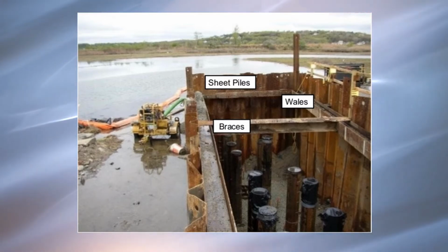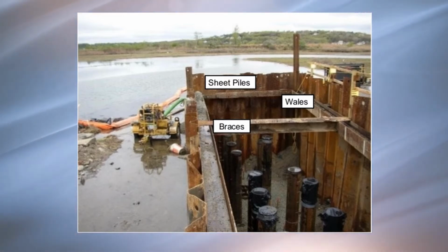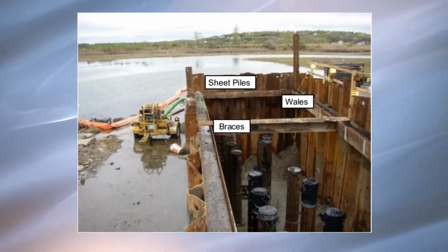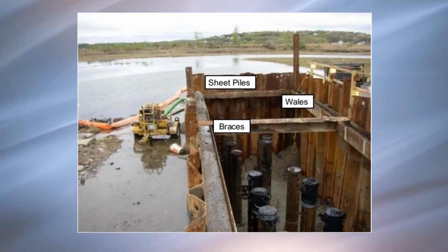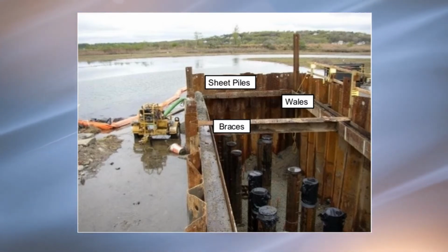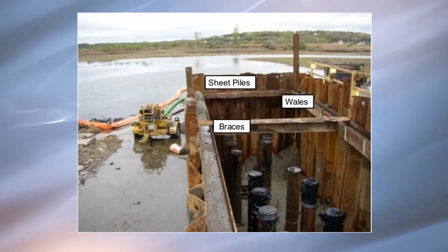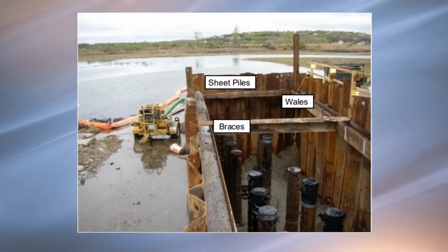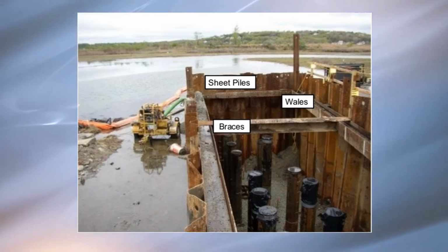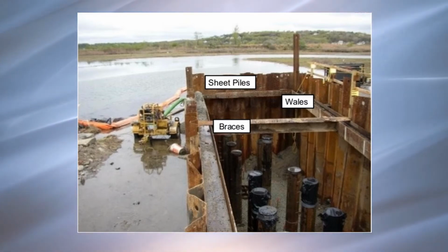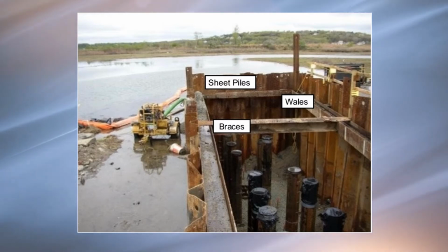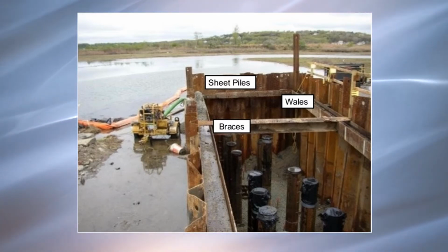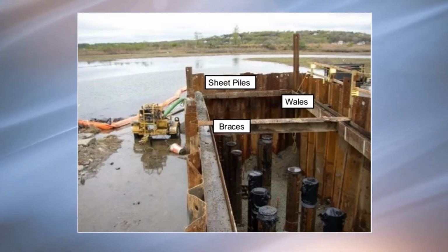Sheet piles are preferred due to their ability to penetrate many types of ground, thus achieving deep penetration, which provides resistance to inward movement at the bottom of the excavation. The ability to achieve deep penetration in permeable soil also has the advantage of cutting off water infiltrating into the excavation.